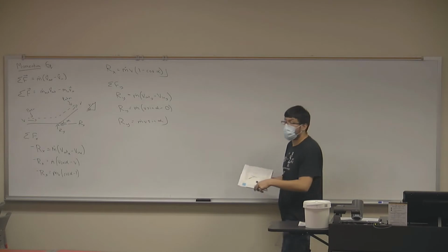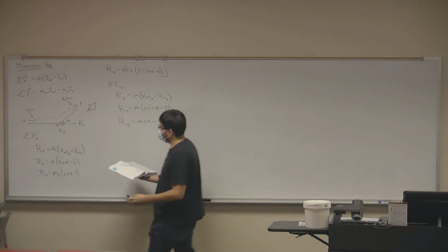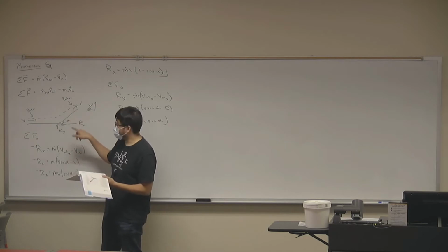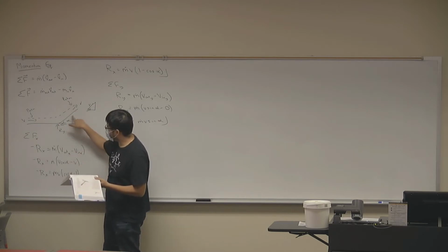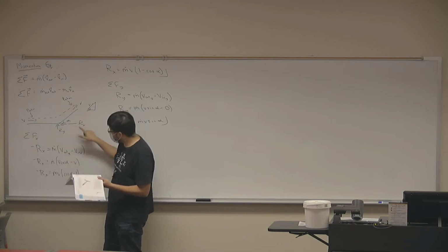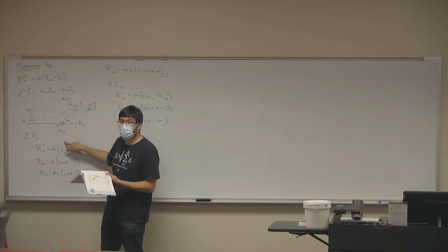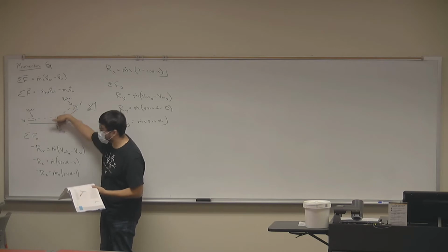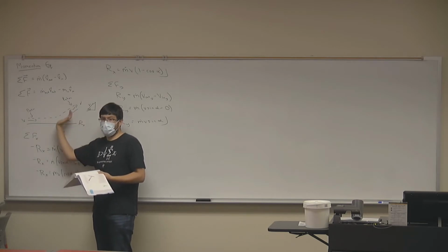Yes? Why is the Rx negative again and the Ry is positive? So when fluid travels through the deflector, it's exerting a force on the deflector. So in order for the deflector to remain static, it needs to apply these two forces. Remember, if fluid travels to one side, the force will push towards the other side. So the deflector has to resist that force.